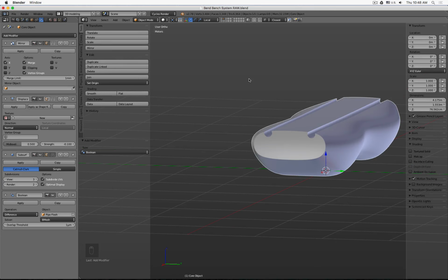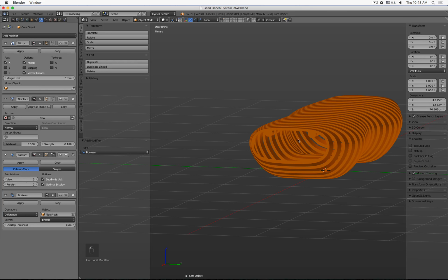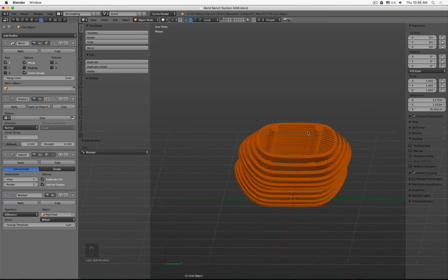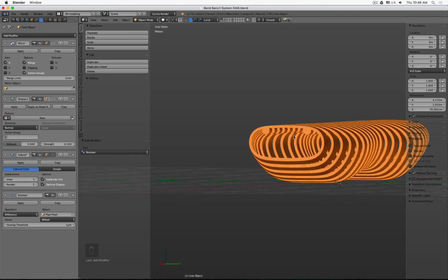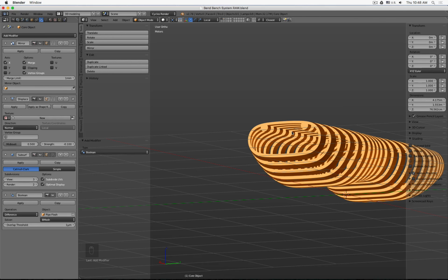Perfect. So because now this core object has the geometry of the pipe cut out, and we use then this to cut out its volume out of our ribs, we end up with all the material still there. So instead of just cutting everything away and then adding something to it, well, we simply only cut away what we actually only need.